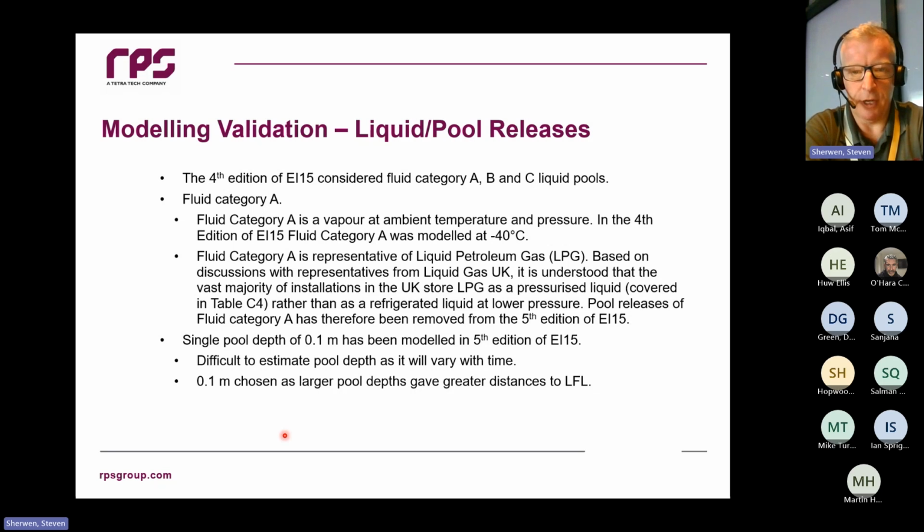We consulted with Liquid Gas UK, and they said that almost all LPG storage now is pressurized rather than refrigerated. So pressurized storage of LPG, if it's released from a hole of the typical size we use in area classifications, such as 1 mil or 2 mil, you end up with the material just flashing off straight away. You don't get a pool. So the decision was made to not include pools of category A liquid or LPG.